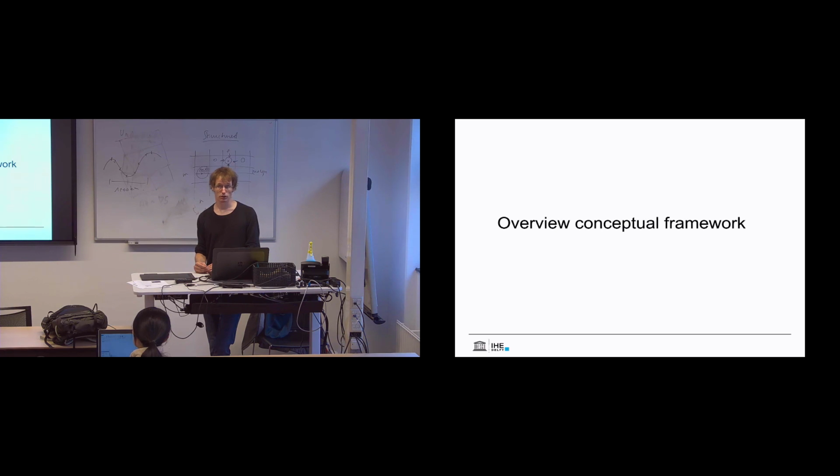And then if you are looking at a problem that combines different physical processes that have different spatial scales, not only horizontally but also vertically, then it's cheapest to use it. Because then you can combine a catchment with a delta area in a 3D estuarine environment, where you have salt intrusion, and then in the delta you might have just a freshwater river flow, and then upstream you might have catchment dynamics that can perfectly be captured in a 1D model.